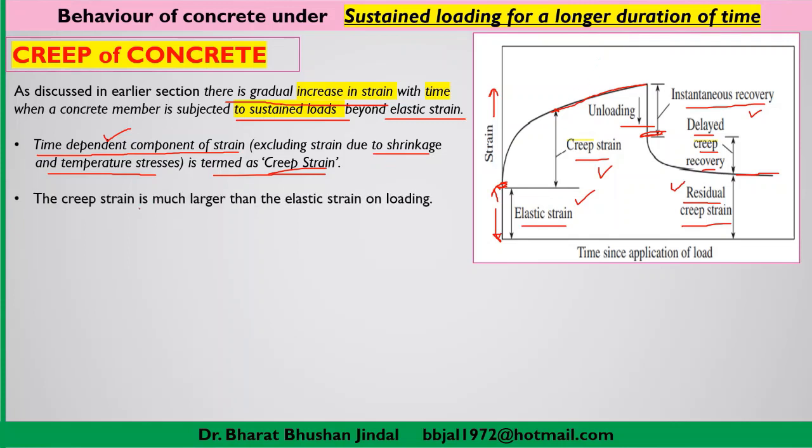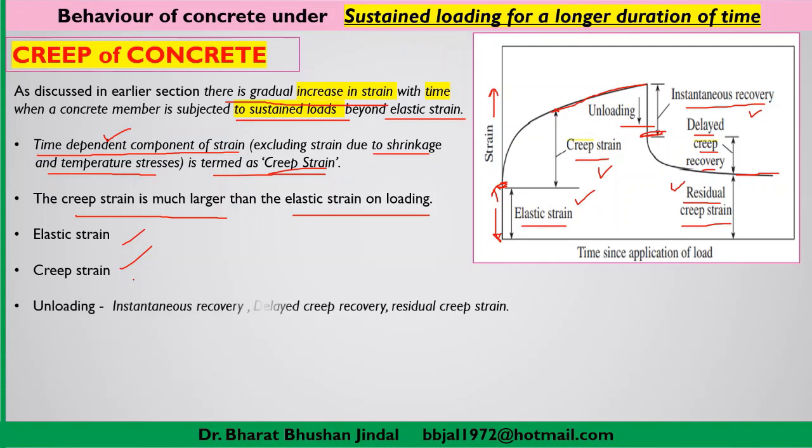Now this creep strain is much larger than the elastic strain on loading. So this is the important point. We have discussed the meaning of elastic strain, then creep strain, and then during unloading, instantaneous recovery, delayed creep recovery, and the residual creep strain. So all the information we have discussed.